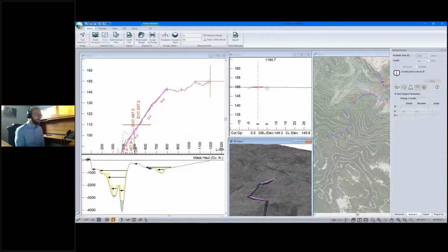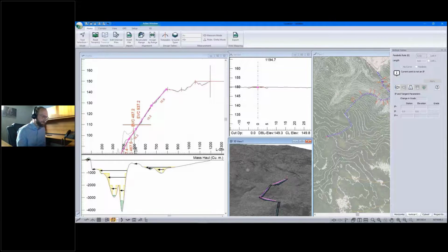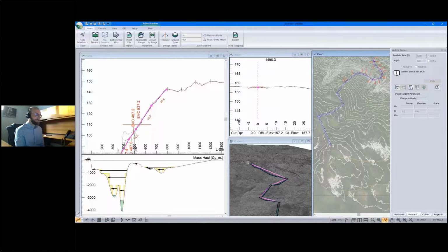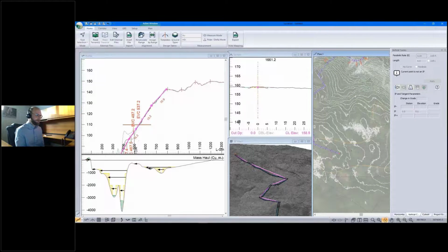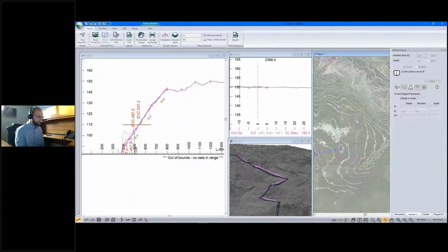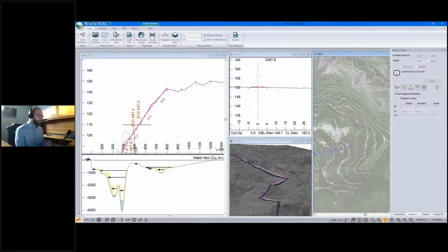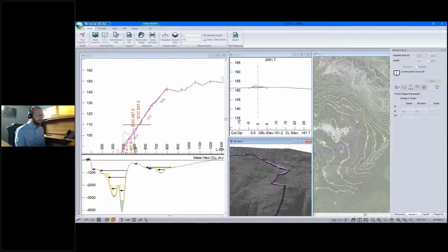And then from a less drainage specific standpoint, but still related, usually those ridges are going to be better material. So it's going to be better material, better drained. It's going to be easier to construct the road, and you're going to be constructing it with better material without having to import that material. Usually with the flatter designs, figuring out your horizontal is less iterative.